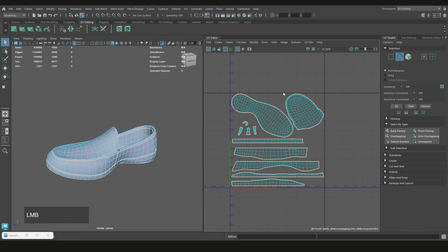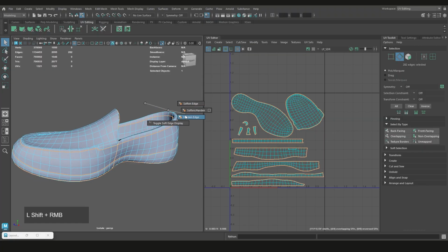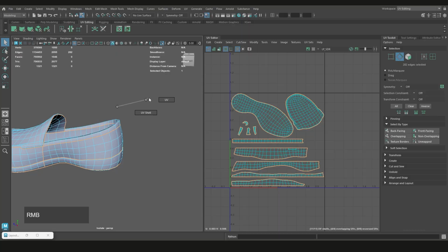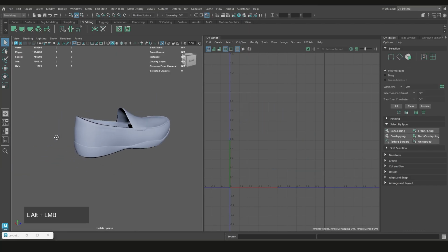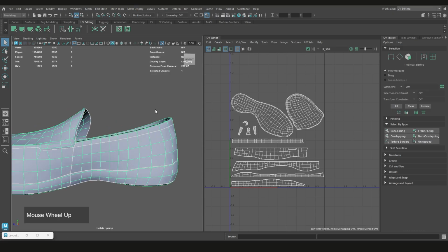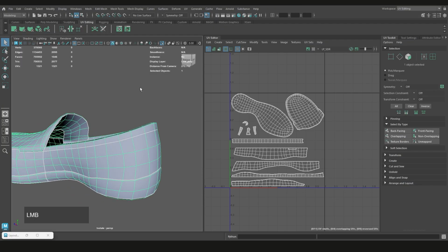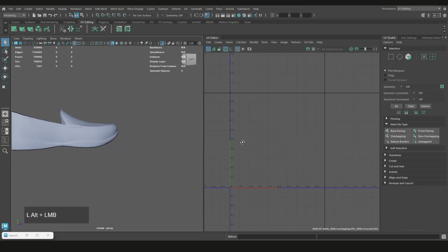Edge, texture borders, harden the edge, yep, and then going over to object mode. Maybe we'll lock, I think locking the normals might be kicking me, yeah, that's what it is. So we'll just leave the normals the way they are. Yeah, so don't lock your normals again.